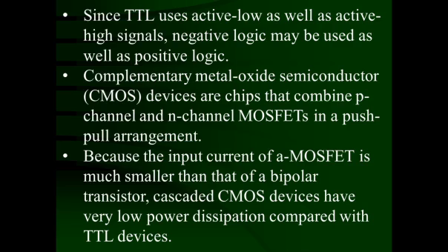Let us consider 0 volt corresponds to the 0 level, and plus 5 volt is considered the high level, that is 1. So when 0 corresponds to 0 volt and 1 corresponds to plus 5 volt, it is considered positive logic. Opposite to this is negative logic.